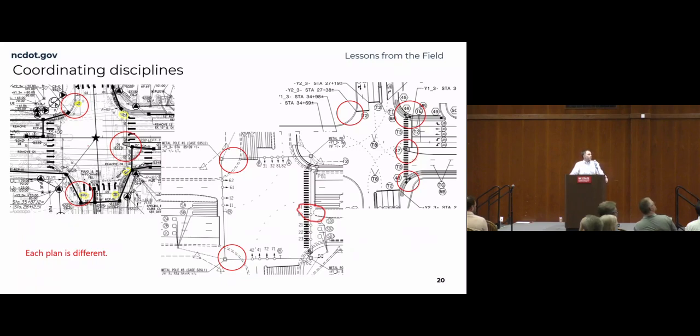And we got some roadway plans. Again, these are just examples of nuances, but we have roadway plans that are showing 2, 4, 5 curb ramps, and that doesn't count one that then shows up on the signal plans as a median island cut through, and then the signal plans don't match either one of those. And when we start having the conversations in the field, it's usually the signal plans that are the ones that, of course, because they've been timed and designed accordingly.